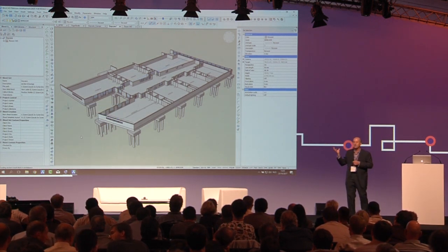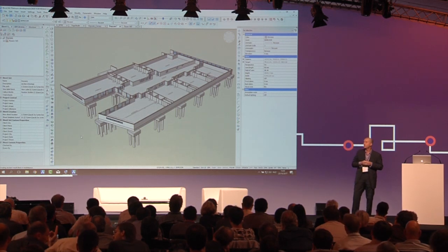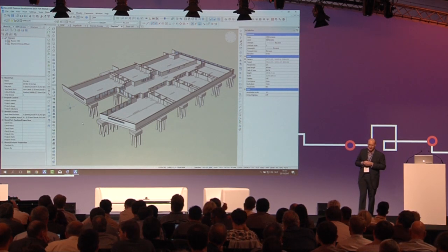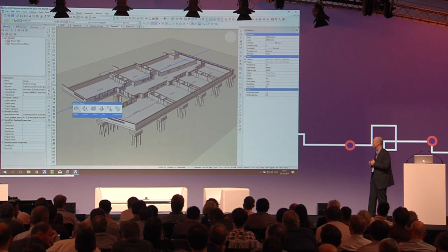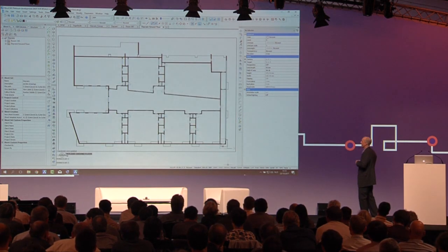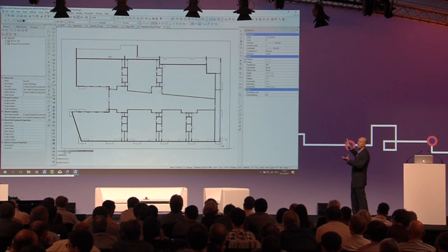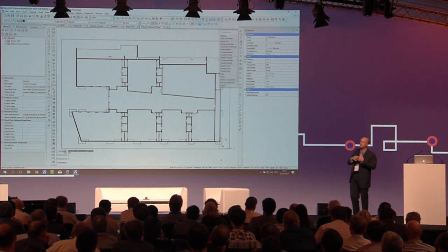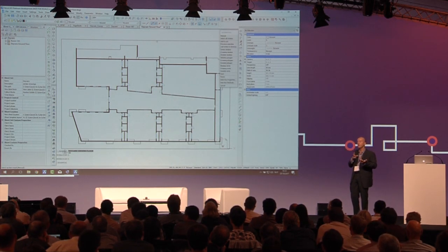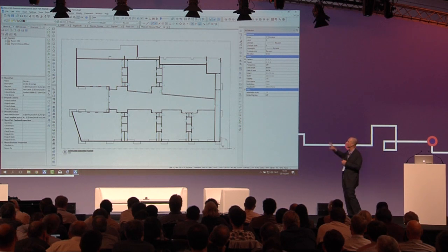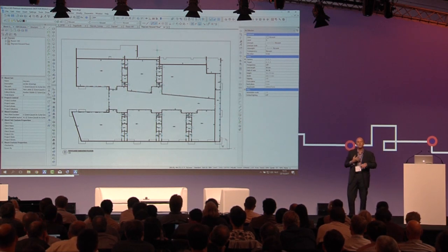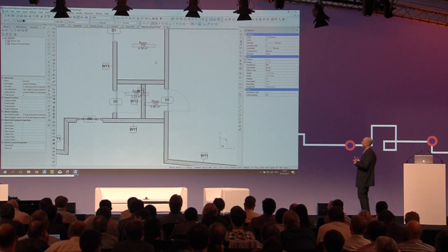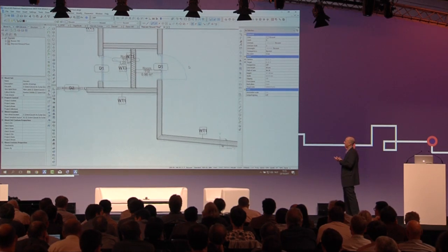So now let's look at another one that's working to reduce the tediousness. We can activate the section, the plan view, and generate that just as a starting point. And then we can go to that viewport that's been created on a new sheet. Now, if you look at this, hey, great, we got the floor plan. But there's no tags right now. But if we want to use the new version 18 feature BIM tags, which as the name implies, is going to apply tags to components. So doors, windows, walls.